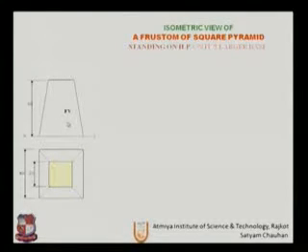So this will be the front view, and the sizes are given as 20 mm will be the upper height and 40 mm will be the base. So total height will be 60. This will be the top view and this will be the front view. So the orthographic drawing is given, so we need to produce the isometric view from this orthographic view.